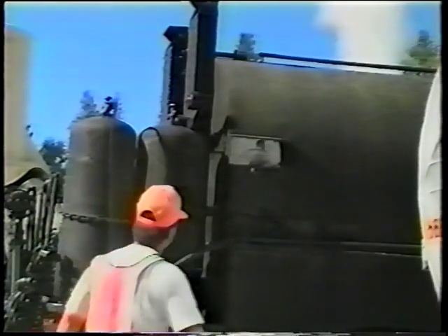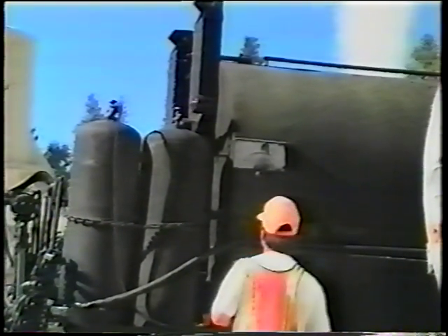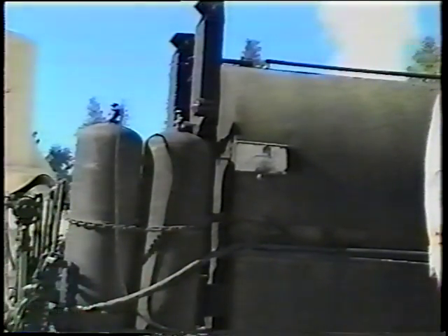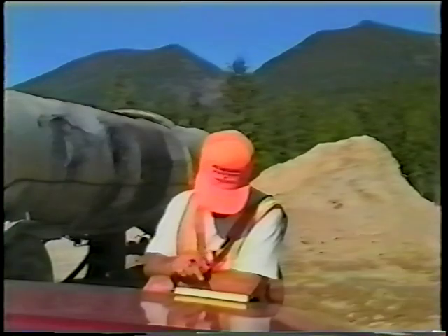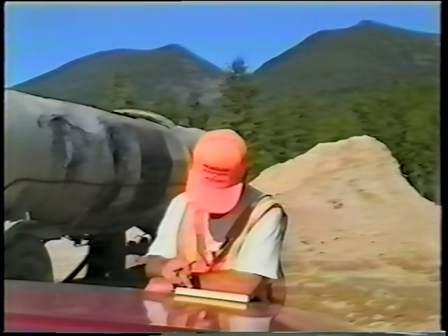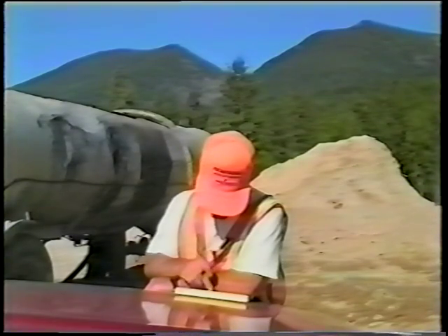After the material has been applied, be sure to record the number of liters remaining so you can calculate the application rate. To do this, you divide the number of liters of tack applied by the area covered: the length of application times the width in meters. The rate is so many liters per square meter.